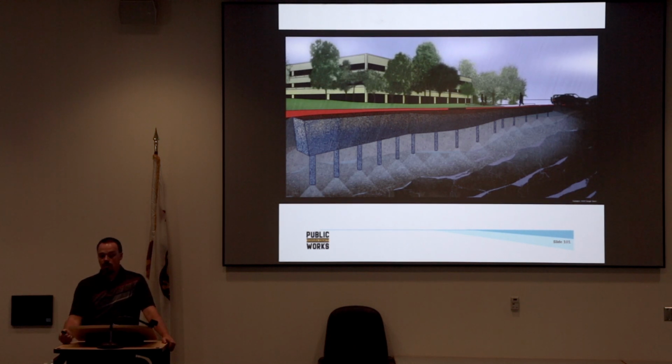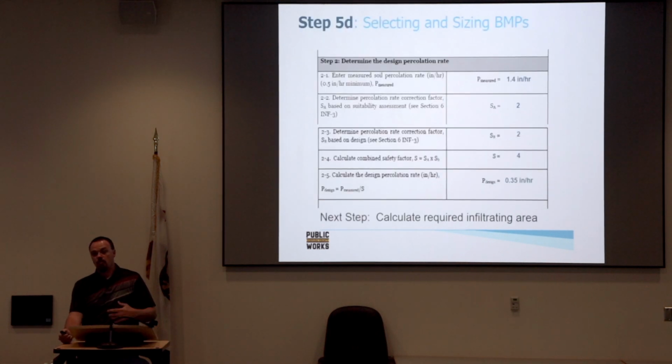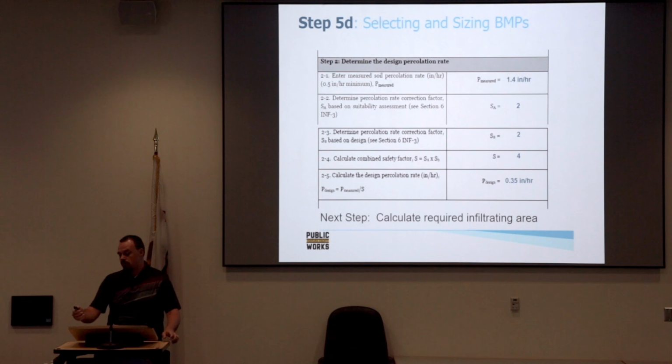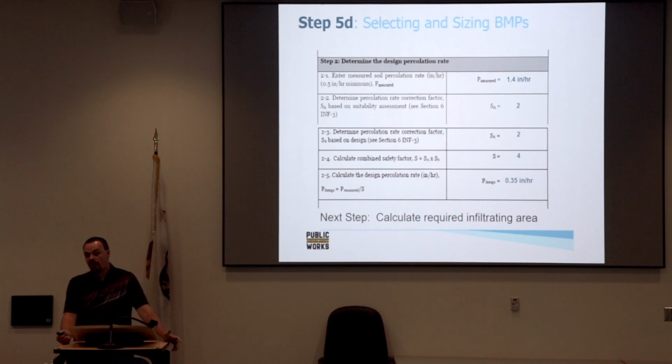So in this case, we did our geotechnical investigations, found groundwater at about 30 feet, and so even going down 15 feet, we know that we're able to meet the 5-foot separation, and we did the GeoTracker research as well to verify that the local wells that have been checked and things like that, that we're not going to be running into groundwater issues. So in this case, we have, I think it's over 400 of these 1-foot diameter dry wells throughout the Government Center below the pervious concrete. And we are able to infiltrate about 700,000 gallons every rain event using this system. So that's just one way of getting around some soil issues, and shows the importance of geotechnical testing to find out what you can actually put in the ground.